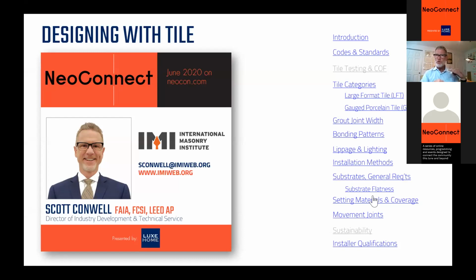And that's great. You can specify an FF 65 all day long, but it's not a guarantee that floor will be 1/8 of an inch in 10 feet. These two tests don't talk to one another. So you could specify a high FF or FL number and still have to prep your concrete, would be my advice.